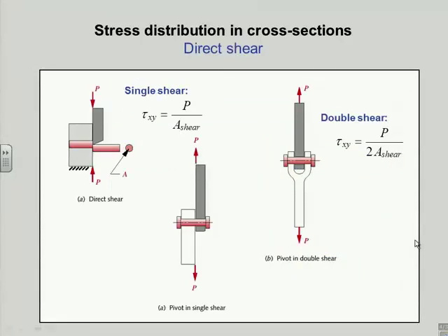Okay, here we have a different sort of loading, which is also very common in machinery. It's called direct shear. And you may know that a cutting instrument is called a shear. And the upper left-hand picture there actually depicts what is a shear. You will find one in a machine shop. If you want to cut a piece of steel, you take it to the shear, you put the steel in under the blade, and you step on a pedal, and a blade comes down and goes whack right through the steel like a big scissors.